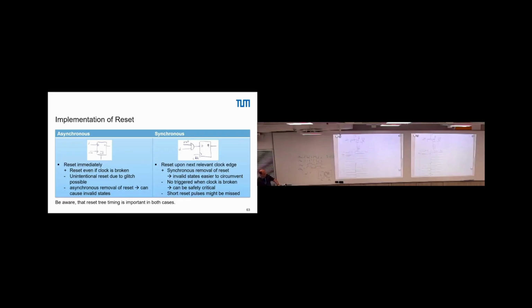Good. So what would happen if we implement at that position just a flip-flop? Effectively, we synchronize this. I do not want to draw it on the paper, because at the end there's a slightly different solution. But effectively, the idea is to put it here. So you have here your external reset, here your clock. This part not really, because you have the delays, but at least this one here.